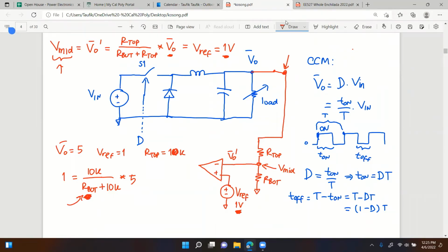That's the mechanism for setting the output voltage. It's a very simple circuit network. The difficulty is not setting up this part; the difficulty is setting up the compensation. We'll talk about that in this chapter next week.